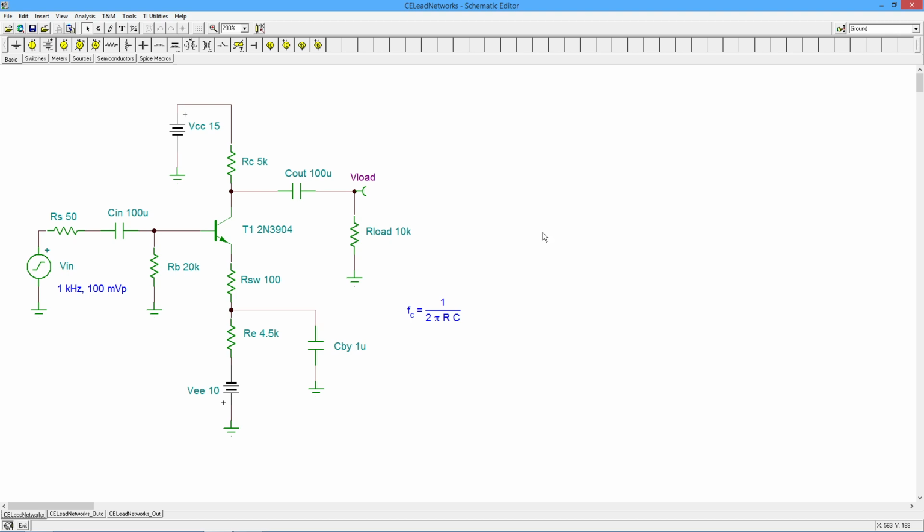You can analyze the lower frequency limit. And one more thing in passing. You're going to see the same kind of configuration with other circuits. We have common collector emitter followers. It's going to work out kind of the same way. We're going to have FET amplifiers, junction FETs, JFETs. Similar kind of thing. You can use this same technique to find out what's happening at the low end on those as well.